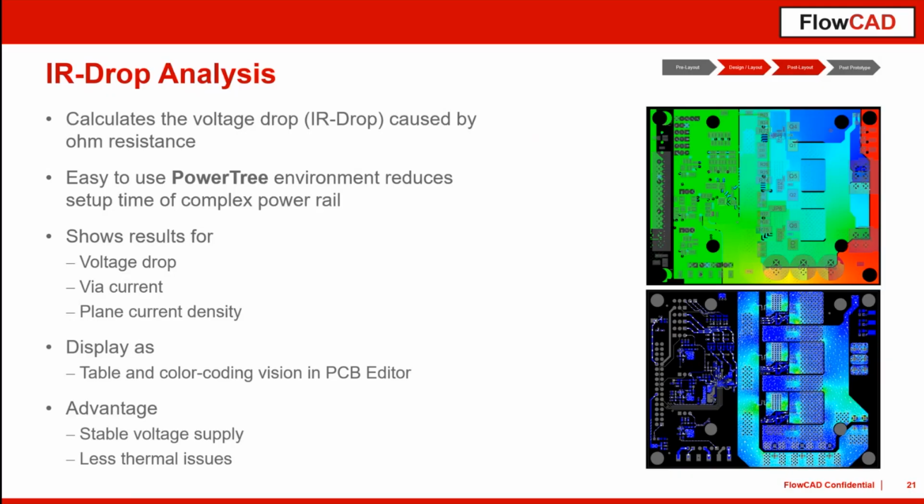the simulation. But once we have more complex designs, that means you have some filters, design filter schematics directly after your voltage regulator, like inductor, capacitor, or whatever else, and a lot of unnamed nets, then I would suggest to use the so-called power tree.